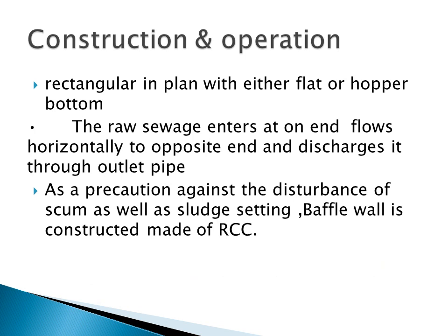Now coming to the construction and operation, the septic tank is rectangular in plan with either a flat or hopper bottom, and here through the inlet the raw sewage will be coming, and the effluent will be coming out through the outlet. And sometimes the scum that is formed on the top of the septic tank and the sludge that is deposited at the bottom will be disturbed by the current. So in order to prevent that, baffle walls are constructed, which are normally made up of RCC.